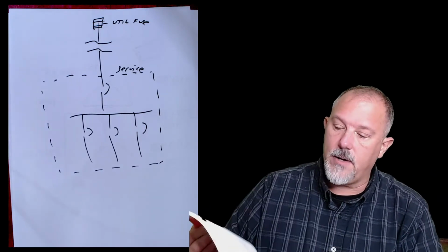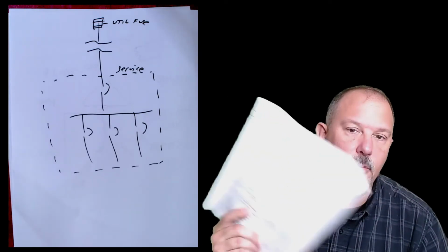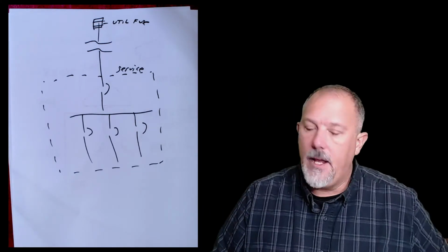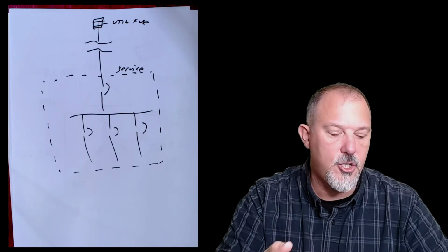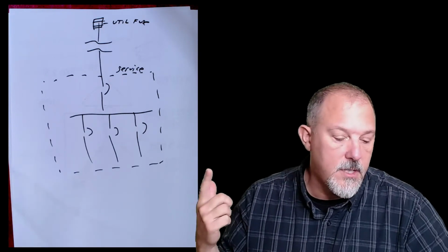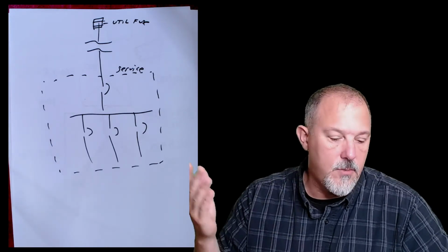The goal was to try to align with 130.7(C)(15)(a), the table method in 70E. And what does the table method in 70E require? The type of equipment that you're working on, the maximum available fault current, which they want you to mark this equipment with. That was one of the options in B.